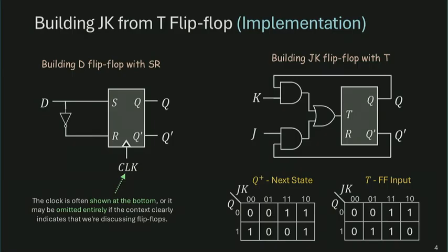And one thing I want you to pay attention to is sometimes the clock is usually denoted by a small triangle. Sometimes we put it on the side. Sometimes we put it at the bottom. But they really mean the same thing. And the clock is often also omitted if the context clearly indicates that we're talking about a flip-flop. Right, so don't worry too much about the representation. As we put down this box and we tell you it's a flip-flop, then you can assume that the clock is right in there.